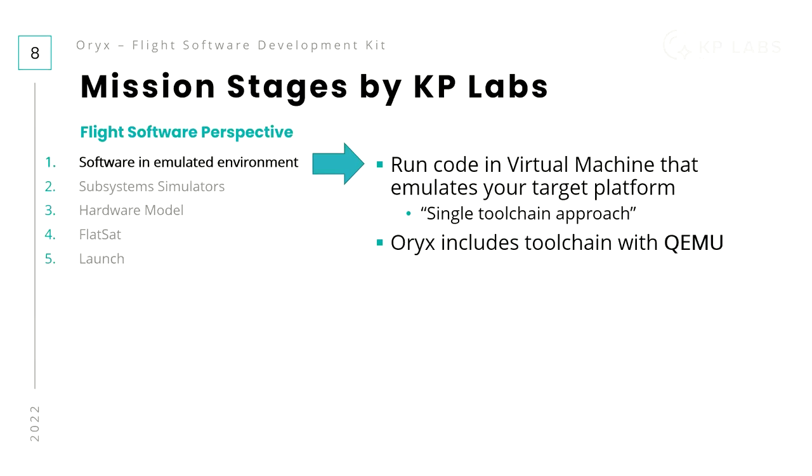So what we'll do is set up QEMU, which is an open source virtual machine, to emulate the Cortex-M architecture for us. So we can take the entire toolchain for Cortex-M and start writing code using that toolchain. There is an alternative approach that compiles for a local PC and tests the code on x86, x64 architecture that's common in modern PCs.